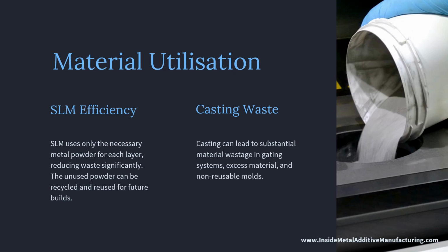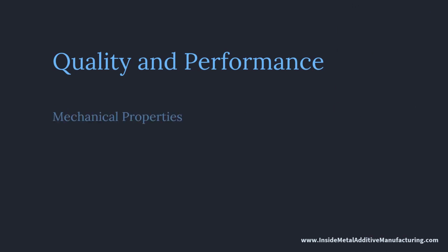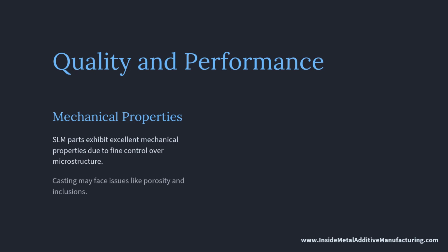Looking at the quality and performance of manufactured parts, SLM parts typically showcase excellent mechanical properties due to the fine control over microstructure provided by the technology. Traditional casting, however, might encounter issues such as porosity and inclusion, which can compromise the mechanical integrity of the parts.